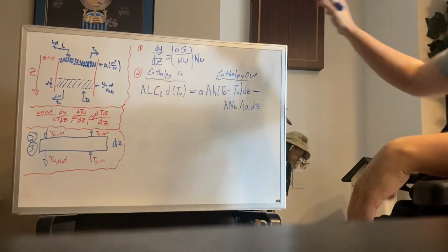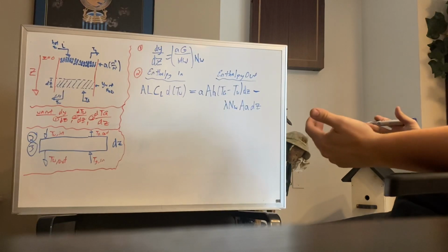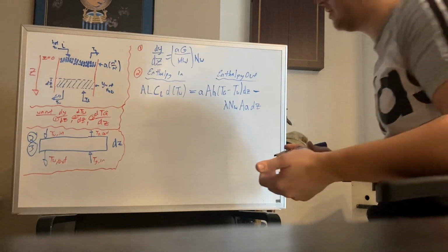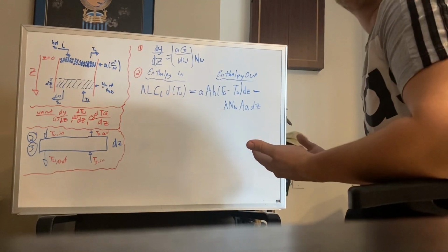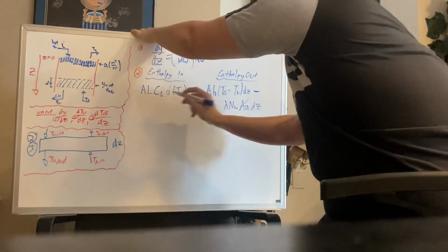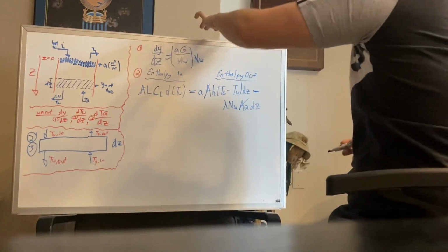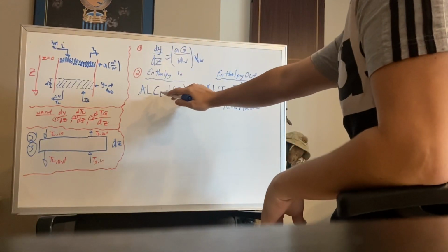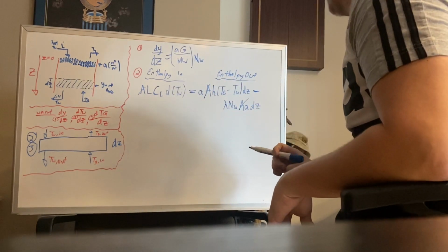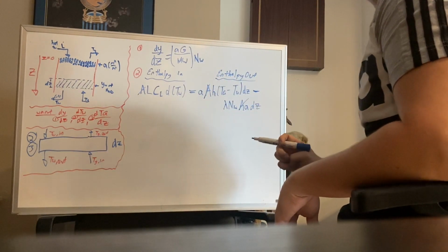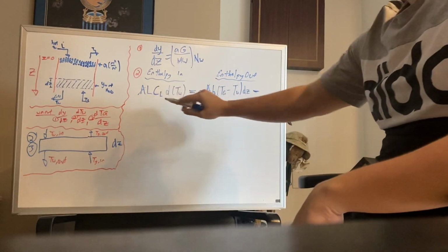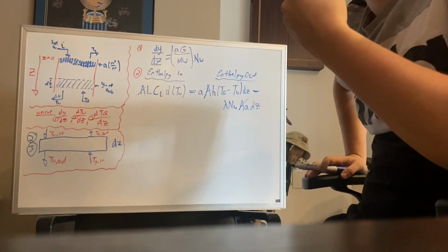And so now that we have this equated, it looks pretty involved for the most part, I would say. At least it lets us see how we can easily change it. So like I said, these A's will cancel out, so we don't have to worry about that either. And that'll leave us with the liquid flow rate multiplied by the heat capacity of the liquid phase multiplied by the rate of change of the water. And what we can do to make this a little easier is divide over dz and divide over L, or the liquid flow rate multiplied by the heat capacity of the liquid.